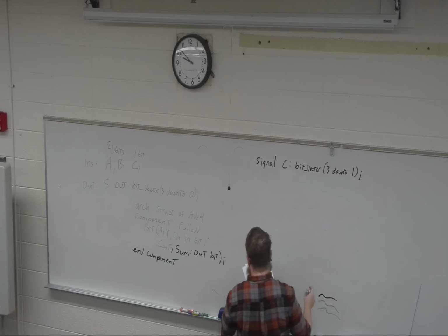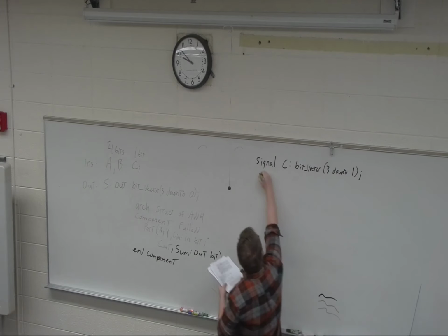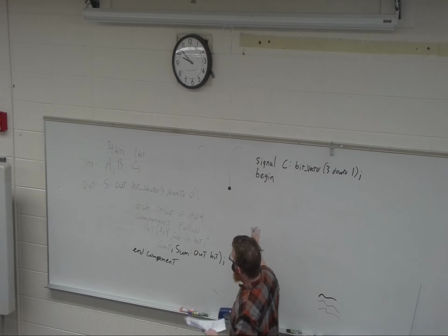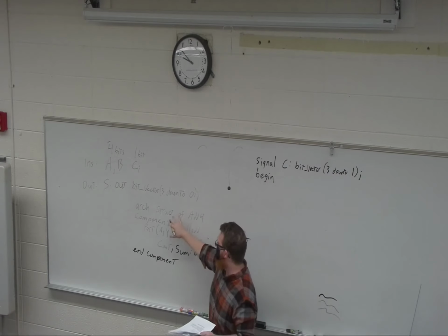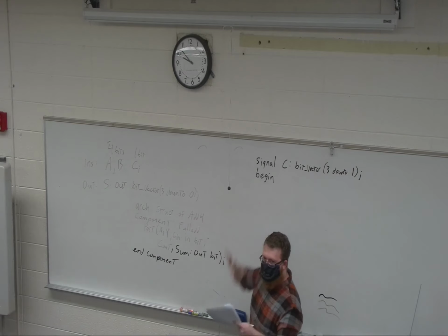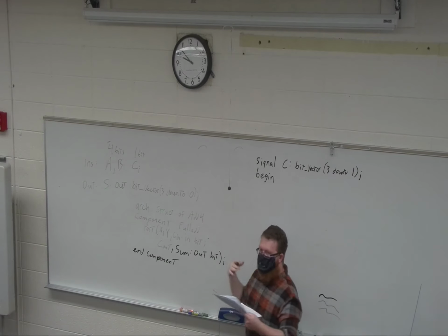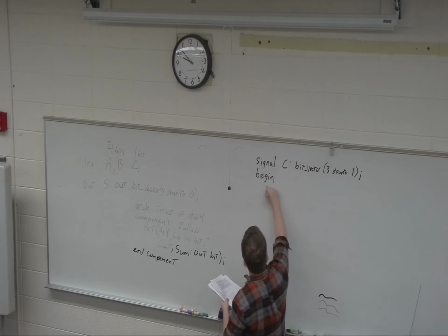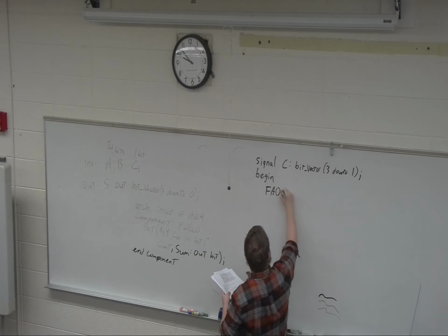And now we're going to write the logic for the entity of the add4. So we've done it for the full adder, and we're going to stick 4 of these together, but we don't want to rewrite all of that. So we use what's called port maps. The first thing that you do is you give it a name. So we're going to start with full adder 0.